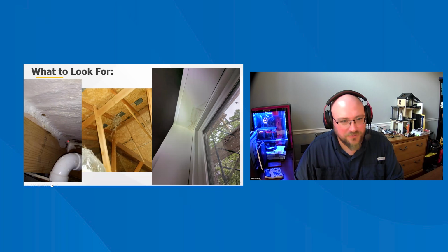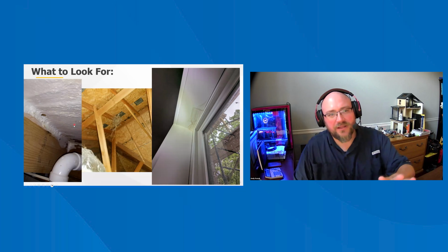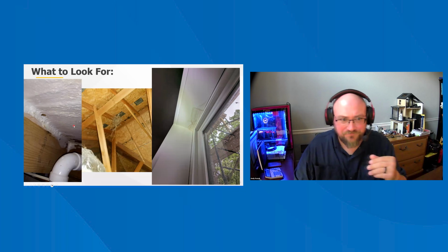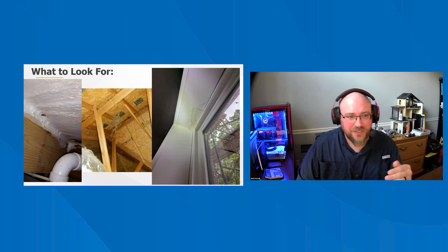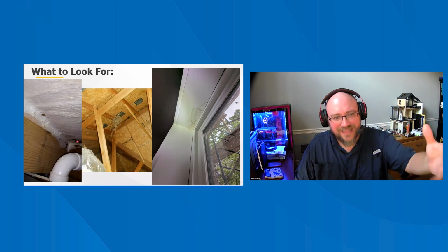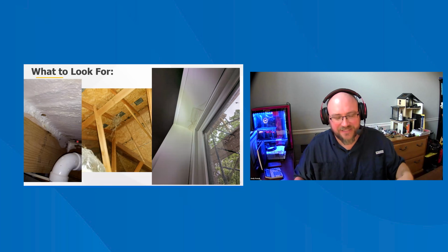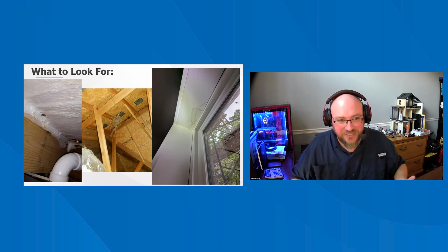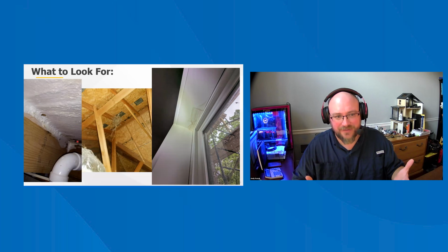So this is all mold against the subfloor in this crawl space. This is the best indicator of why the kraft paper needs to be against the floor. If there was a leak against the floor, or if the paper face was against the subfloor, it would have come through the kraft face into the insulation and then dripped out of the insulation. You would have seen it. But the kraft face actually kept the water inside the insulation and kept it against the subfloor, and that's what